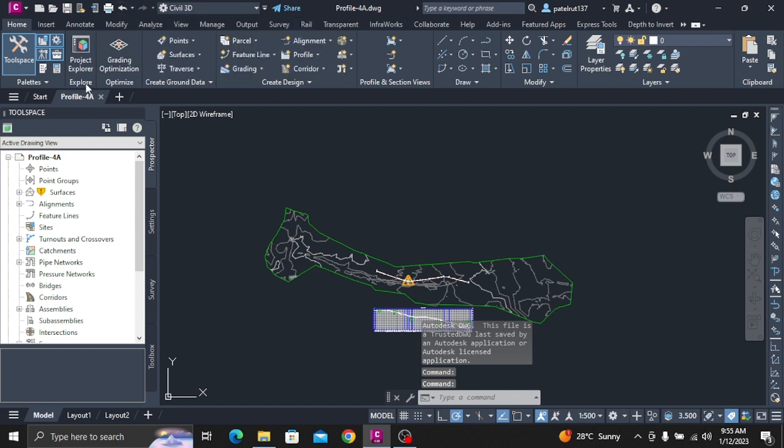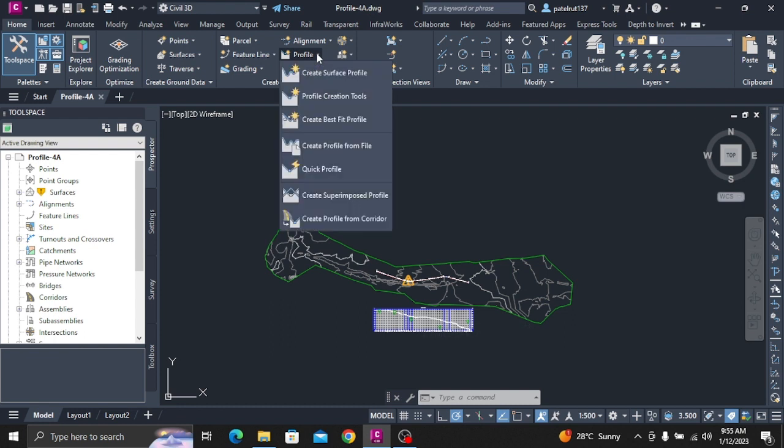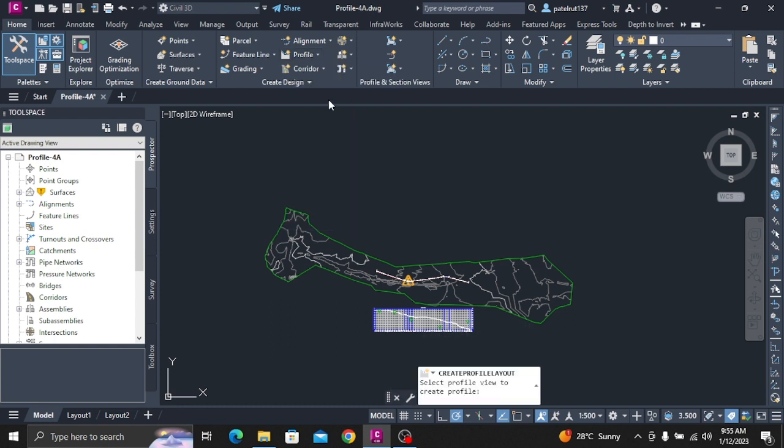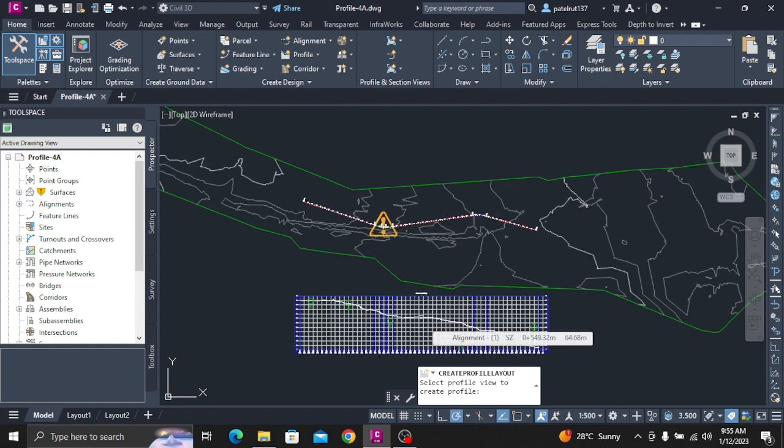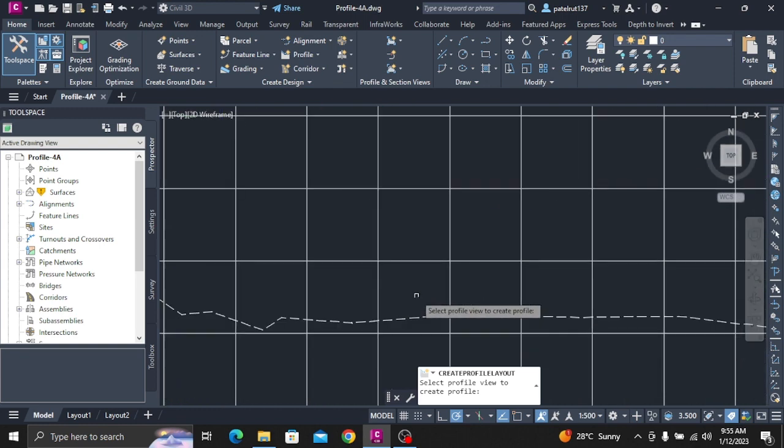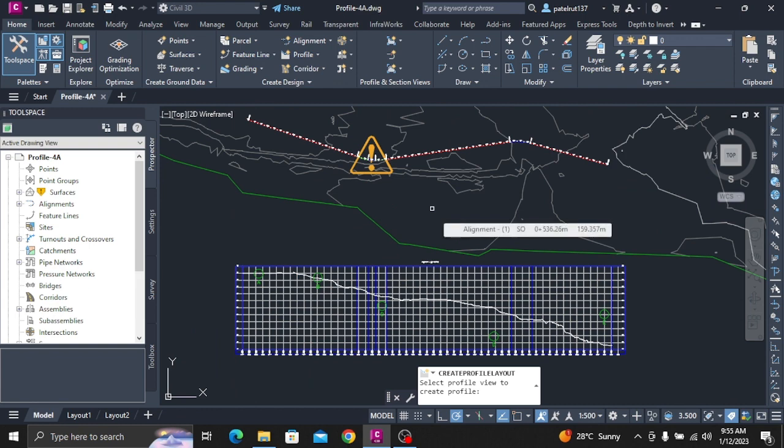In the right viewport, select the 3D polyline that crosses between stations 0+060 and 0+080. When you select the 3D polyline in the profile view, notice that the 3D polyline in plan view is highlighted. Drag the left grip down toward the bottom of the profile view. Repeat steps 1 and 2 to examine the new elevation value.